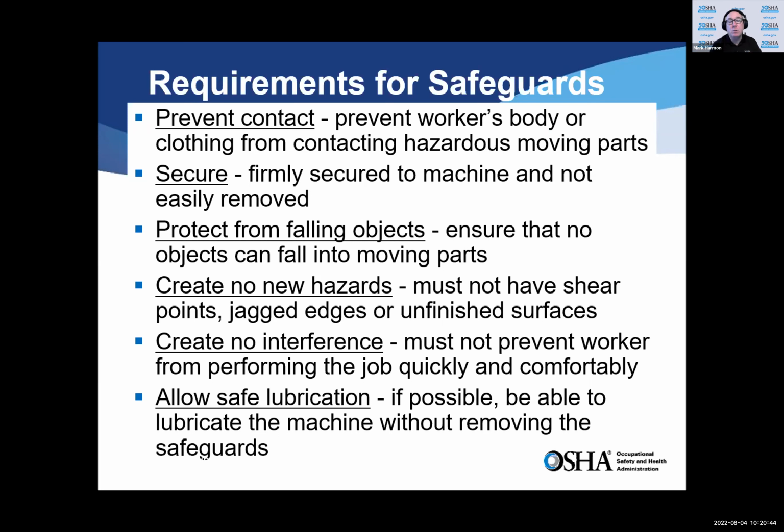Second bullet point: firmly secure to the machine and not easily removed. I would say what they're speaking to there is the guard itself. If you have a guard on a machine, it should be attached in such a way that it is not easily removed. I always give people the example: if you have a tool such as a wrench where you tighten the fastener, the hardware, the bolt, the nut, I would say that would not be easily removed, and somebody couldn't just work it off with their fingers.